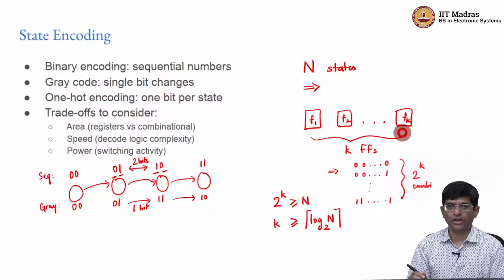When you have literally only one of the signals as non-zero, you can basically just OR those states together and say, if I want, for example, the elevator up button, the motor up button to be active, it should be in this condition where it's in the moving up state, right? But there might be some other signal which is basically in multiple different states, right? And that signal would essentially be done as an OR of the different states in which such a scenario could have arisen. So the decoding part of it becomes extremely straightforward.